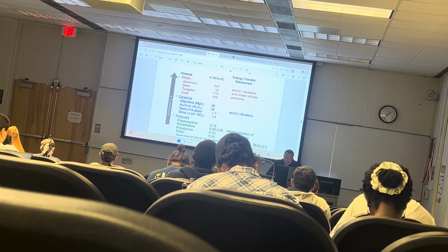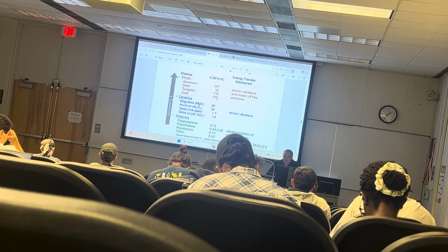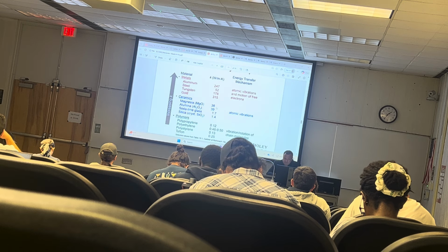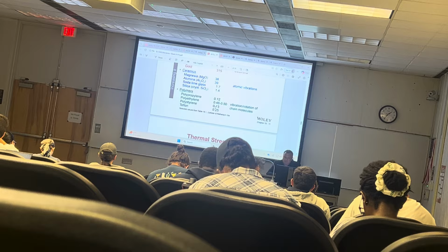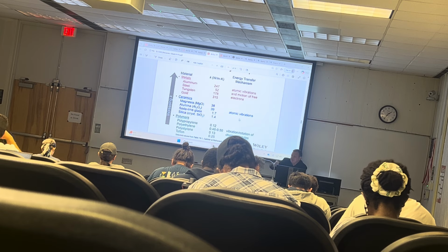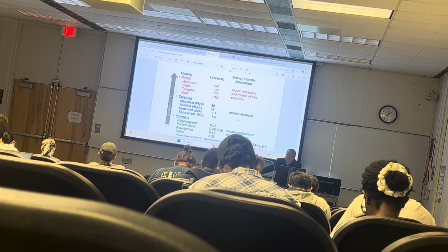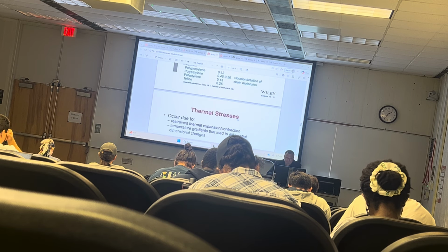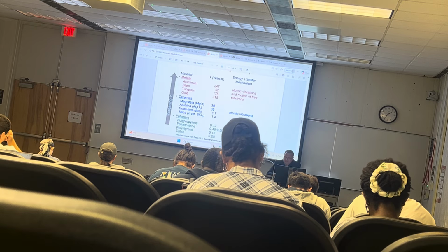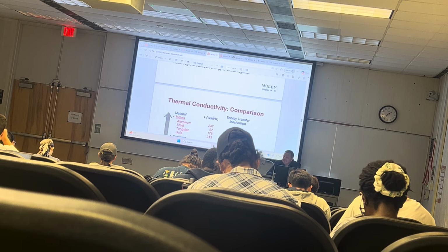Okay, the highest conductors of heat are metals, followed by ceramics, followed by polymers, because, again, this is a propagation of the atomic vibration wave that propagates from here to here. And some materials are very good insulators and some are not. We'll get back to this. But so far we discussed thermal conductivity and the heat capacity. These are two different things.